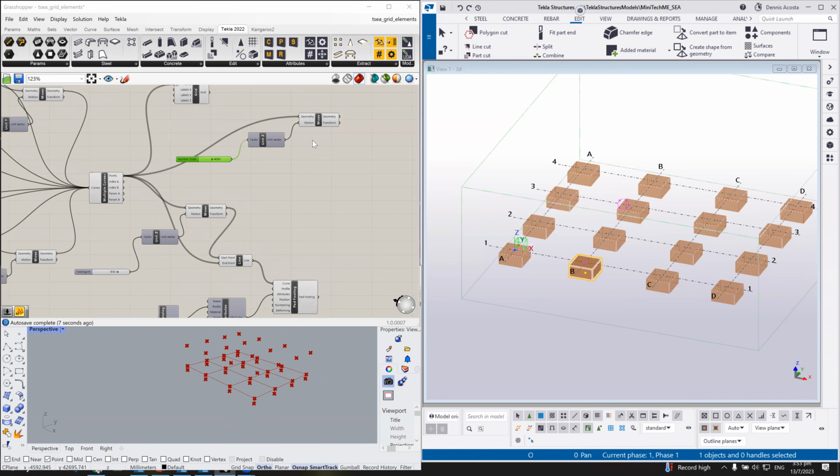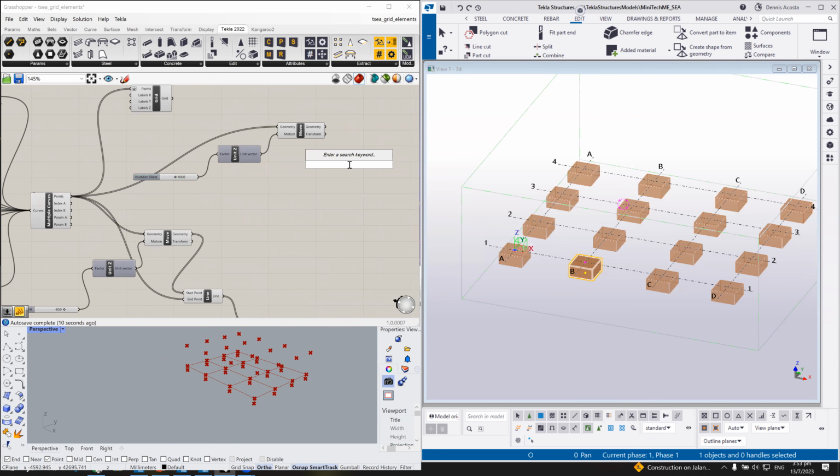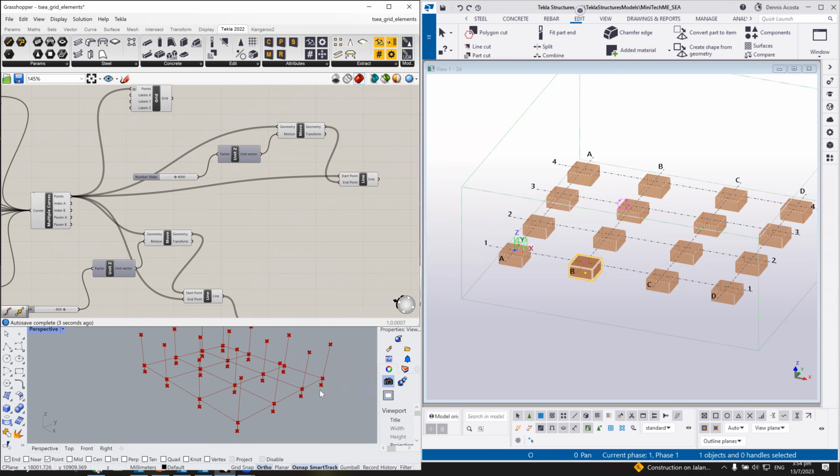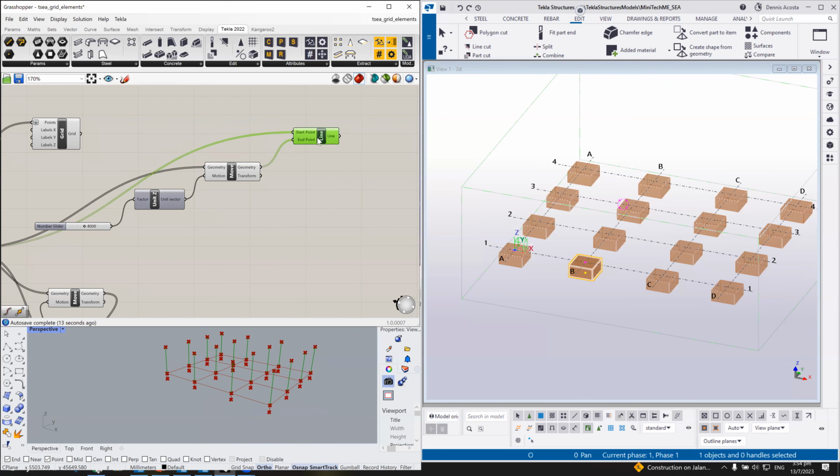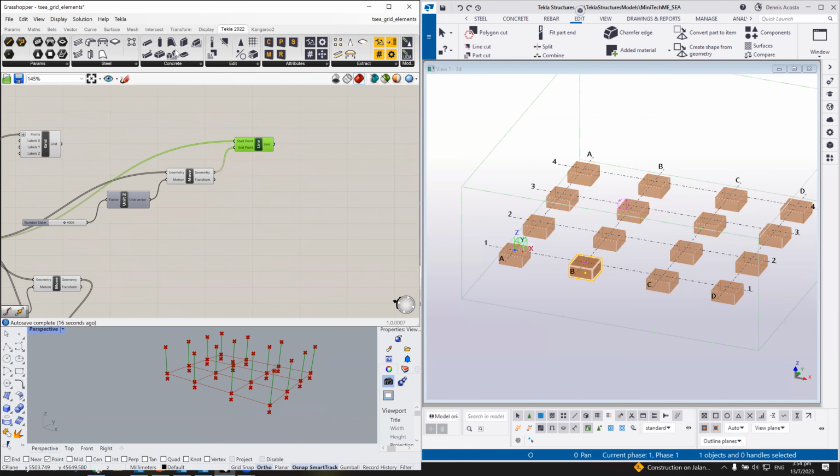So again, if you create the line here, if you create 2 lines here, so the bottom now is this one. That is the start, and this is the end. See here, you have now the line. Again, this line must be converted to the column. From this Tekla Structures dialog box, you can see here the steel column. You just pick it here.